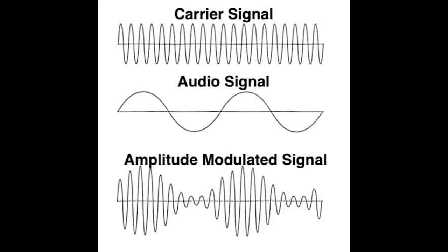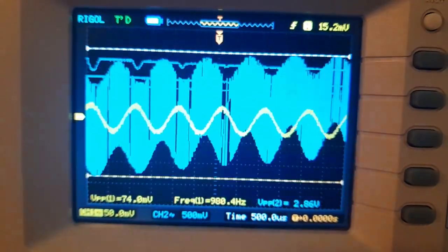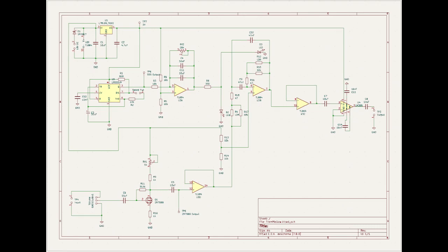The goal of the circuit is to modify the amplitude, the envelope of the carrier wave, in this case the original guitar performance, with a time-varying control voltage. The circuit will consist of the following: an oscillator, an integrator to shape the output waveform from the oscillator, a tunable bandpass filter with a constant Q where the center frequency will be controlled by the output of the integrator, a MOSFET preamp to apply gain to the incoming guitar signal, and an amplifier output stage to make up any gain lost throughout the circuit.